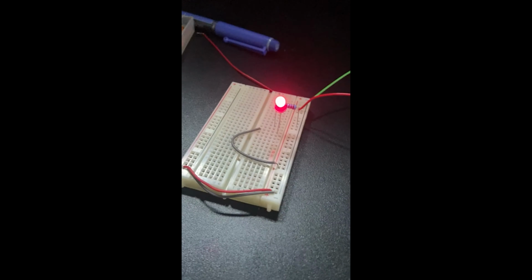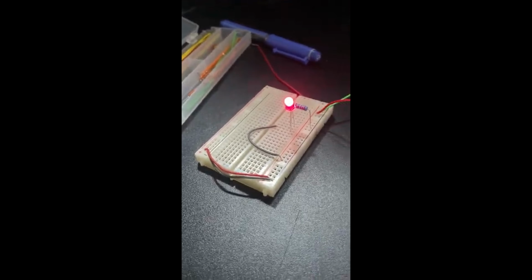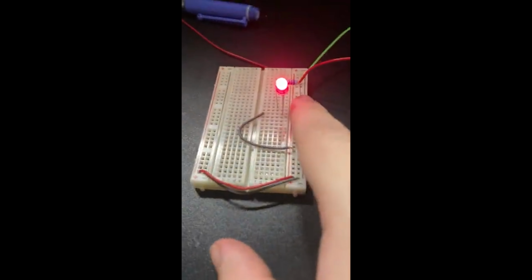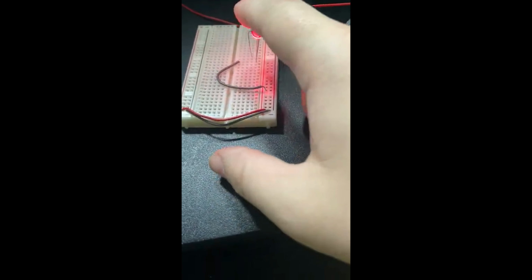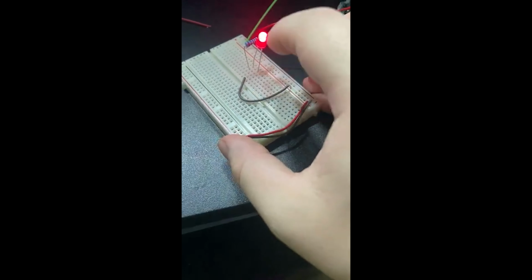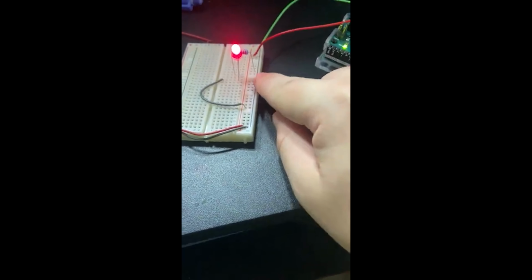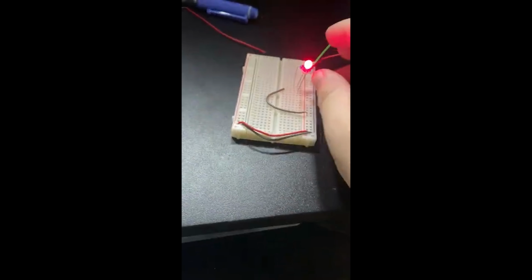Get in. It's in enough. It's in there enough to turn on. So again, the way that this circuit is working is that we are getting 5 volts from the Arduino, and more specifically the USB connection in the computer, but we're getting it from there. It's going into the breadboard. It's then coming out of there into the LED. It's going through the LED and then through the resistor back into ground, which is the same ground connected to everything else. And that's what's happening right there.